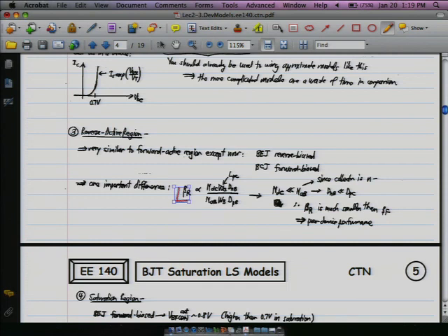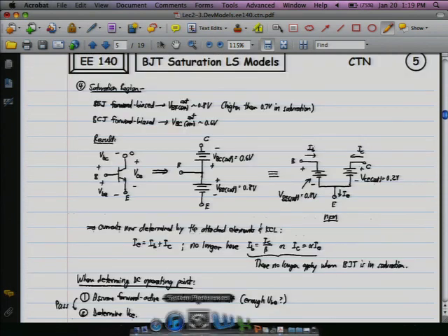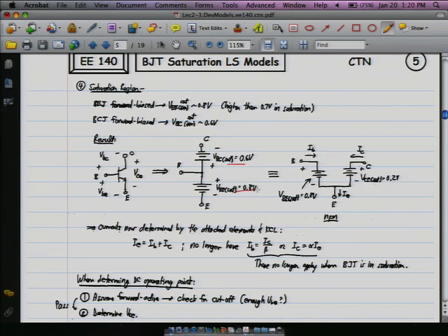All right? So now we can start talking about what's happening in the saturation regions. This is the region where we basically said that the diodes were just forward biased. We have a current path straight through. And so we can basically just represent these diodes as being voltage sources. They're both on. So that's exactly what you see. There's not much more to it than that. These diodes are on, and they're going to flow current appropriately. You do notice that there's a little bit of a difference in the voltage across these diodes, and that's because of the doping differences.